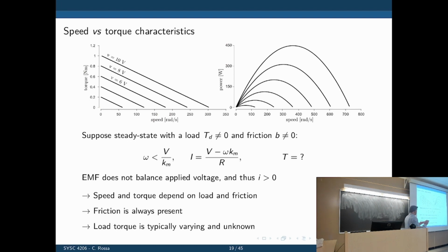So the torque you develop will make the motor speed up and gain speed. When you reach the point where friction, that is speed times the coefficient of viscous friction, is exactly how much torque you are applying, the result is 0 net torque, meaning that the speed remains constant. And so that is what limits the maximum speed when the motor just spins by itself with no load.